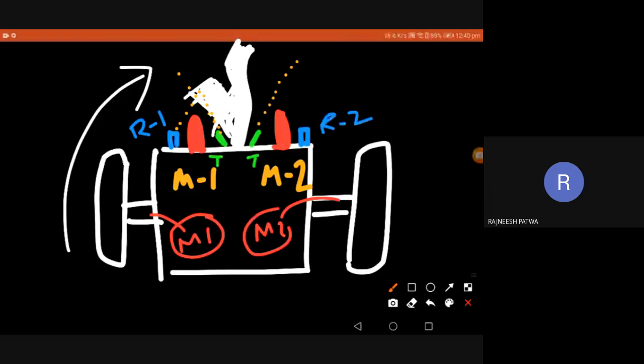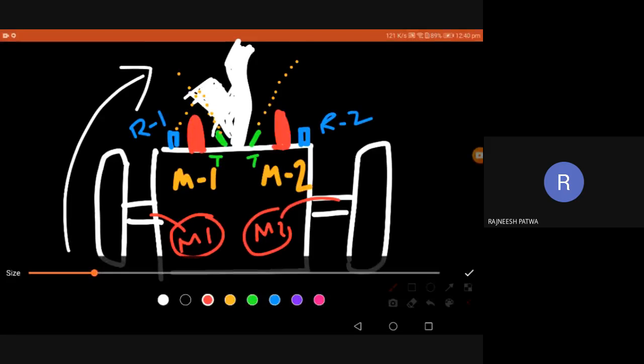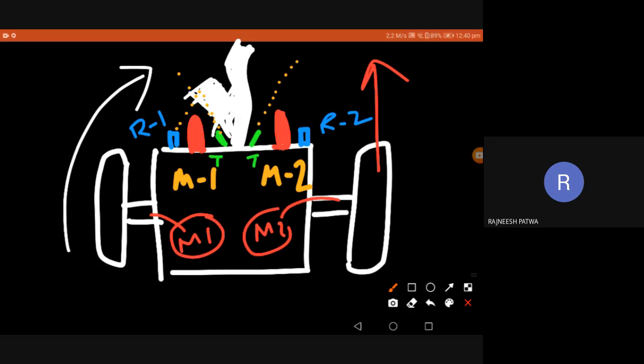both sensor receivers are not receiving any reflected radiation, that means I assume that I am exactly passing over the white line. So I can move both motors, or rotate both wheels, forward. That means both wheels can move forward, so the robot will move in a straight line.